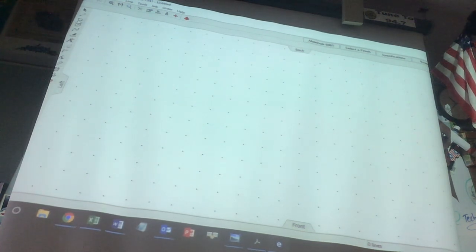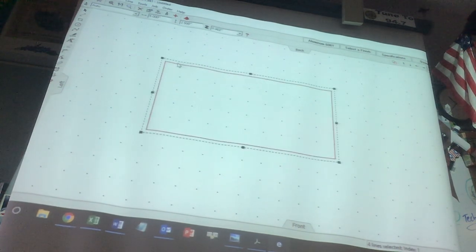I go here. I'm going to make it 2.5 inches tall. If you look up at the very top there, that's 2.5 inches by 5 inches. This is an actual drawing from the drafting book, 5 inches long by 2.5. The depth, rather than being 0.0625, is 1.5 inches. And then I have to make sure that I hit the return key.